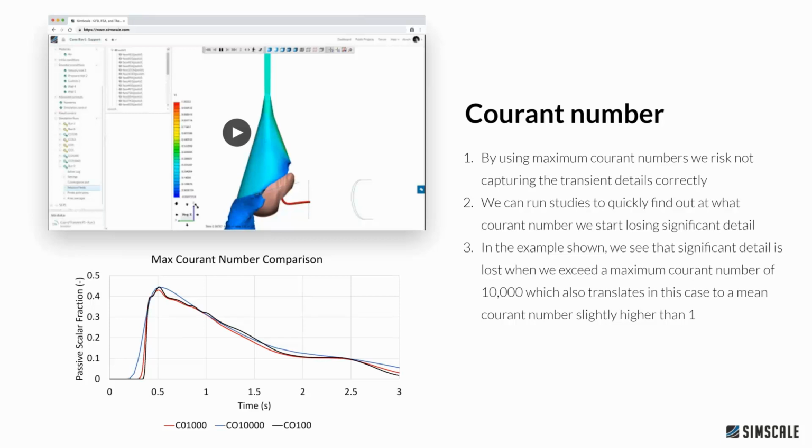So all the time we're making this assumption that in some areas there is going to be steady results. This is absolutely an assumption. So it's up to us as the engineer to decide where the limit is. So we could push it up to 10,000, a million, if your simulation would allow that. But what you've actually got to do is take a step back and go, okay, I'm able to push this simulation this hard and this fast, but am I going to get accurate results out of it?